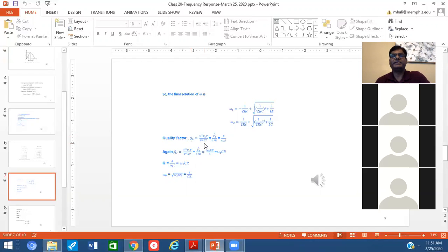Then if you see the denominator, V square G, this is the power consumption or power dissipation across the resistance, and once you multiply it by T, that becomes energy. Now in the numerator and denominator, T cancels and V square cancels. In the numerator, BL means 1 over XL, since susceptance is the reciprocal of reactance.